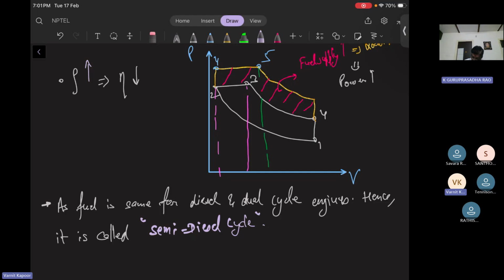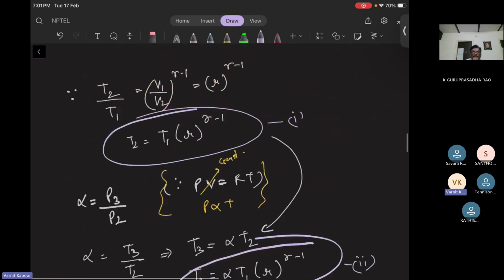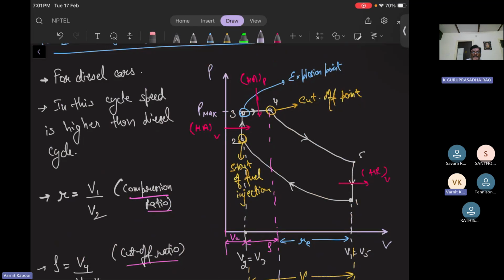Okay. All right. Now let's come to the process of heat addition in detail. In our cycle, if we go back and see it once again, we are adding heat first from 2 to 3 at constant volume, then from 3 to 4 at constant pressure. Why have we chosen this order, first constant volume, then constant pressure? Why not first constant pressure, then constant volume? One could have thought like that, but there is a reason behind why the constant volume is happening first. Let me write here.